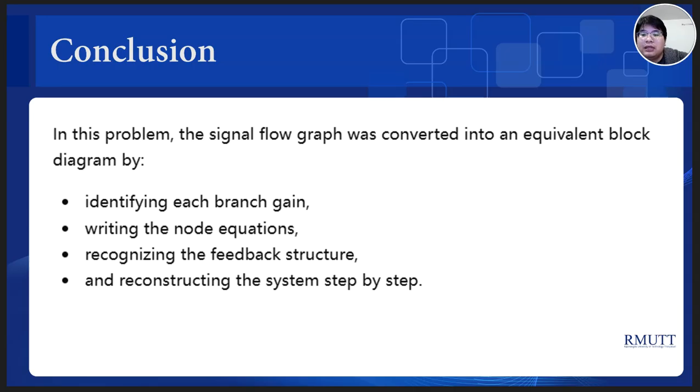In conclusion, this problem was solved by converting the signal flow graph into an equivalent block diagram. First, I identified the branch gains in the graph. Second, I wrote the node equations.